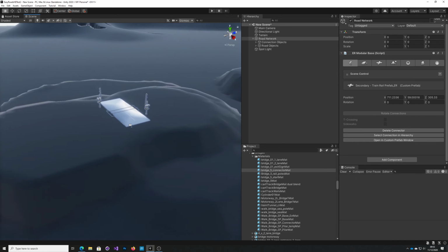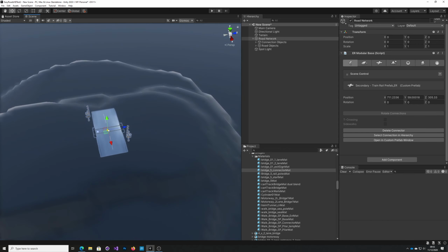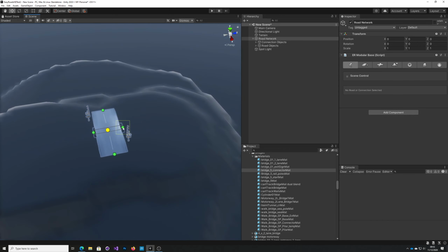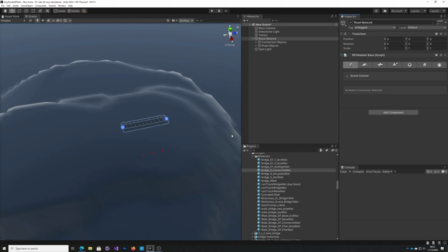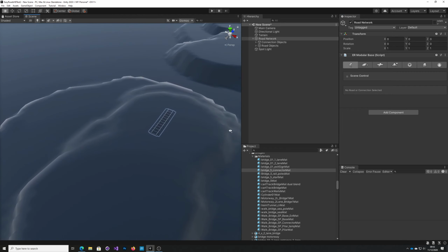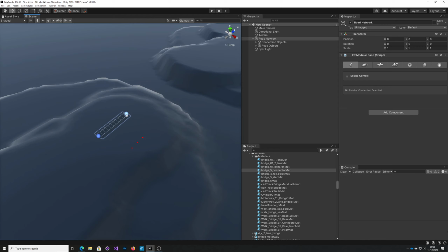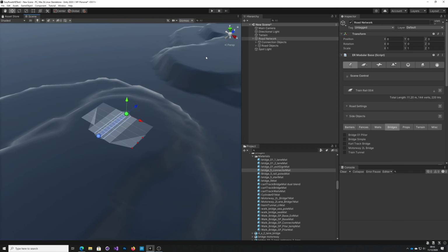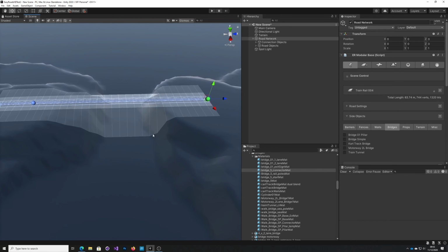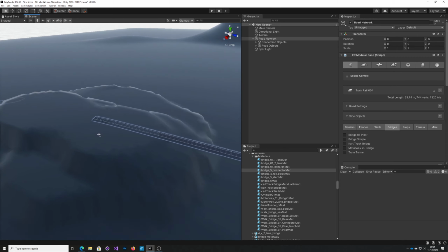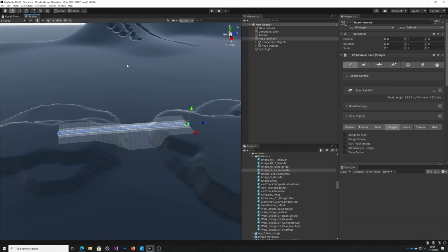Now I need to extend this to give me a track. So it gives me the track. I can come in here and delete the connector. So this is my starting track, and if I add a connection point across the way, you can see that it goes across, and by default EasyRoads is going to try and just create land underneath that to fill that gap rather than create a bridge. I actually want to put a road through here later.